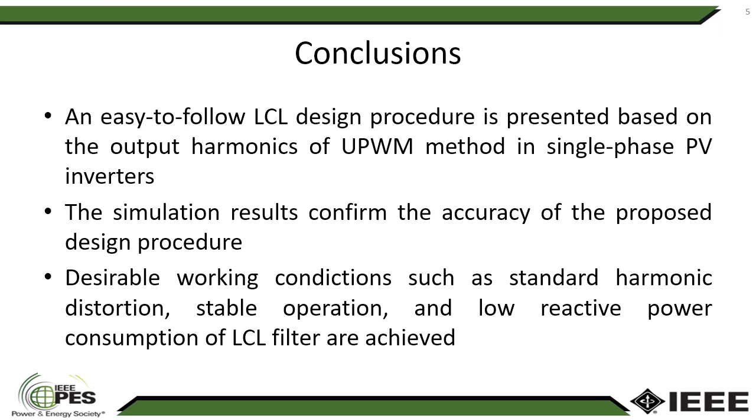As a conclusion, in this paper, an easy-to-follow LCL design procedure is presented based on the output harmonics of the unipolar PWM method in single-phase PV inverters. The same material has not been provided in the literature so far. The simulation results confirm the accuracy of the proposed design procedure. Desirable working conditions such as standard harmonic distortion, stable operation, and low reactive power consumption of the LCL filter are achieved through the LCL filter. Thank you.